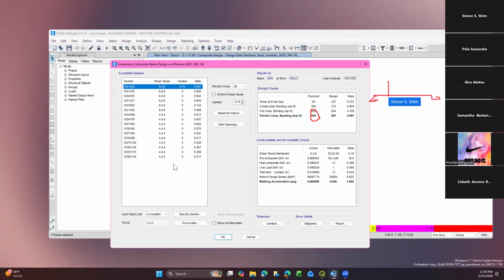So here we have a 2-point load for a 30 feet span, right? Same thing, you could calculate by hand. If this is 64, wait a minute, is 64 the maximum? Yes, it's the maximum shear. The factored shear is 64, so this must be 32.